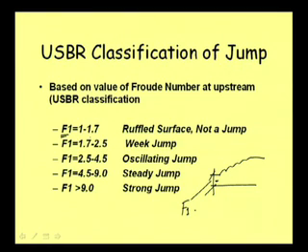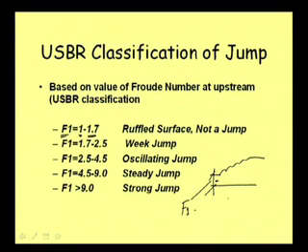Well, now when this F1 is just exceeding the value 1, from 1 to 1.7, for that range of Froude number, it was found that the surface profile cannot be regarded exactly as a jump. Theoretically, it is a jump because the Froude number is greater than 1, but see, when it is very close to, well, here I think it will be better if I draw one diagram.